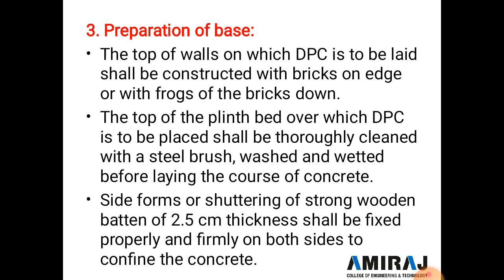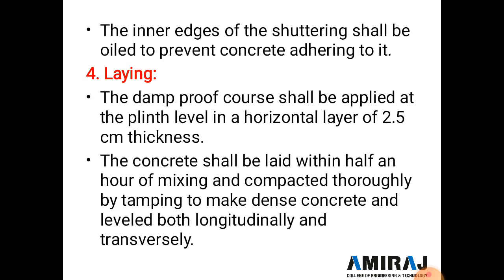Now side form or shuttering of strong wooden batten of 2.5 centimeter thick shall be fixed properly and firmly on both sides to confine the concrete, and the inner edges of the shutter shall be properly oiled to prevent the concrete from adhering to it.